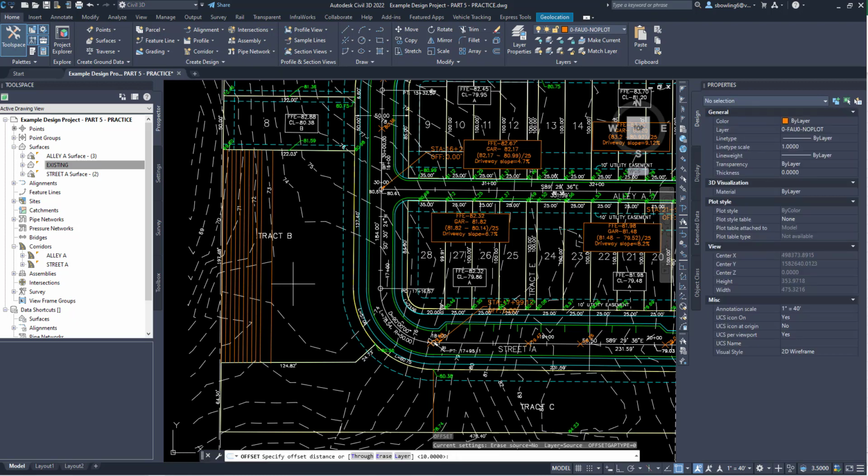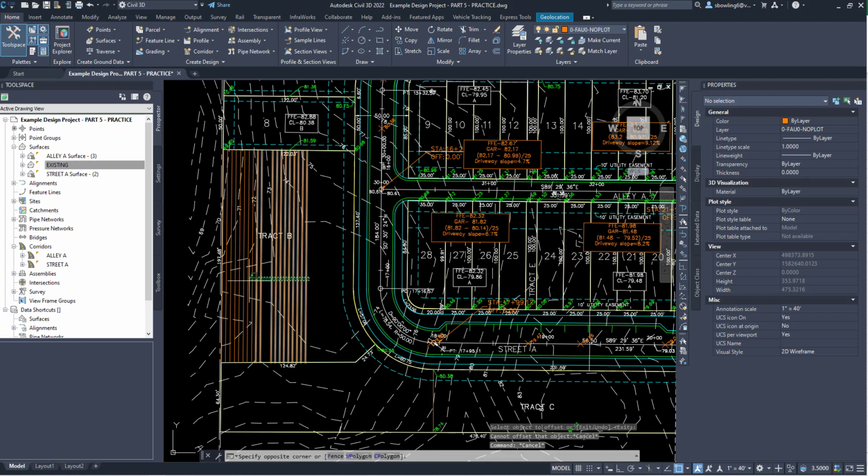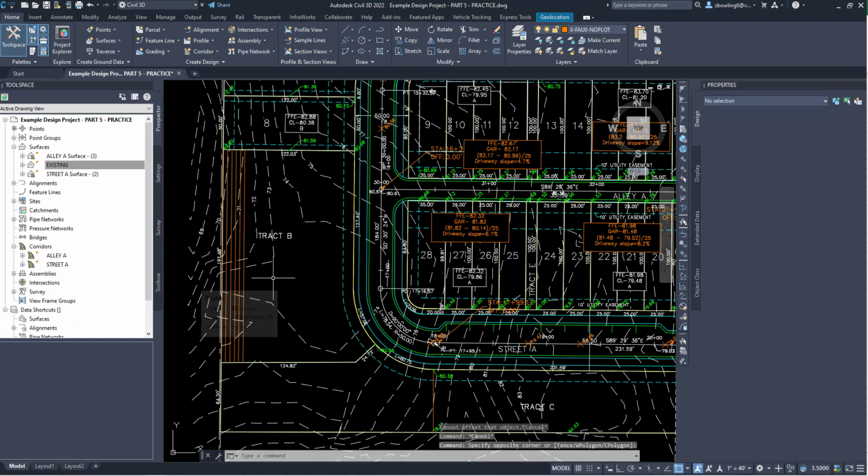Now I go offset of 4 again, so that'd be 79, 78, 76, 75, 74, 73, 72, 71 elevation. I lose a lot of ground, so I don't want to build from this side. I actually want to go downhill quickly and keep my pond here. So I'm going to go ahead and delete that out.